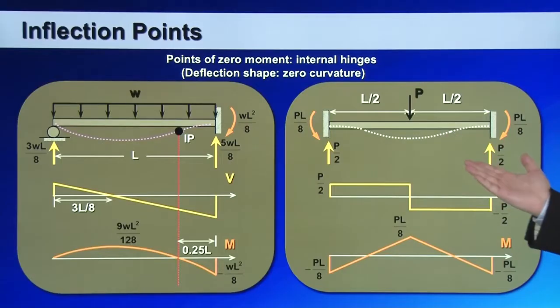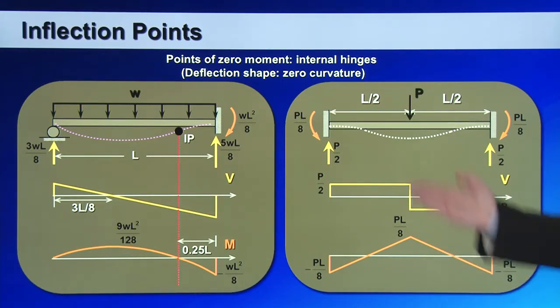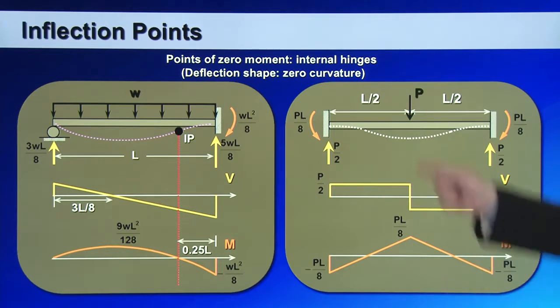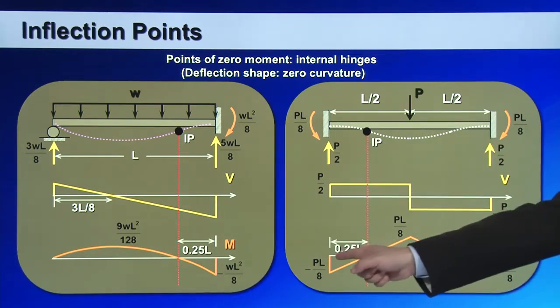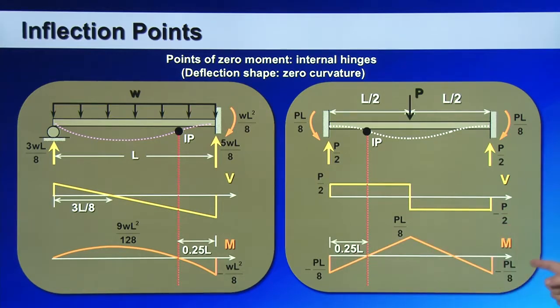Similarly, this is a clamped beam. It's an indeterminate structure. But if you are able to identify or estimate the locations of inflection points early on, then you can use that information to calculate. Detailed analysis shows that there are two inflection points, located, again, 1/4 from both ends of your beam.